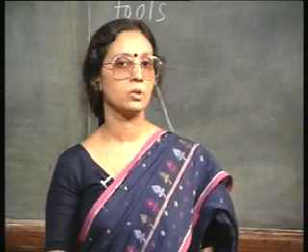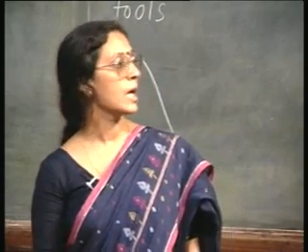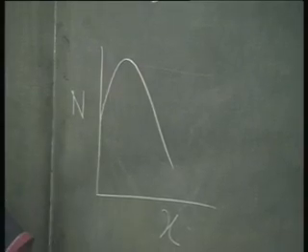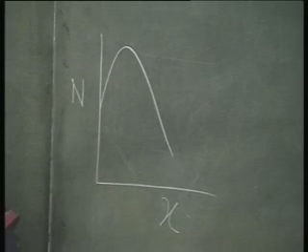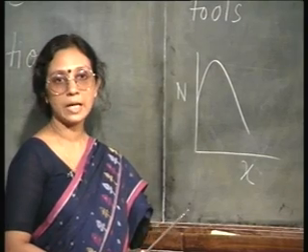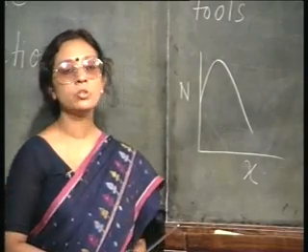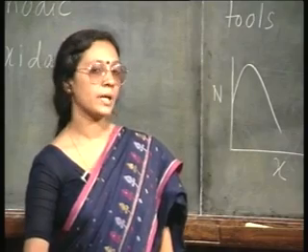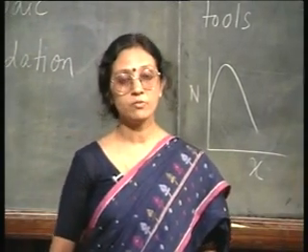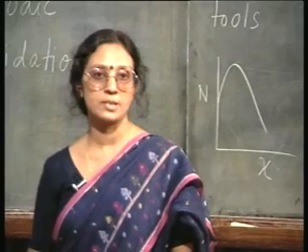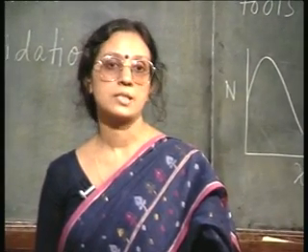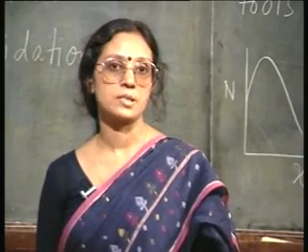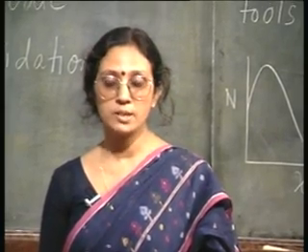So, the thickness of the oxide can be very accurately determined, and one can etch that oxide and measure the surface properties of the fresh surface thus exposed, and keep on continuing doing that in order to obtain the full doping profile. So, even though anodic oxidation is not really compatible with VLSI technology, and it is not a standard processing step, since thermal oxidation is the standard processing step, it still has its usefulness.